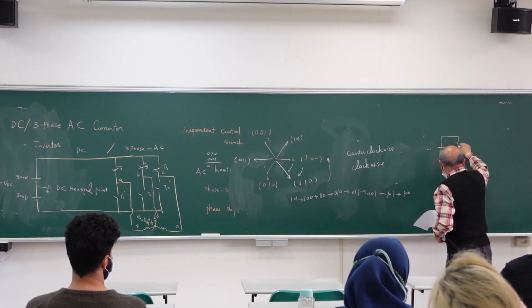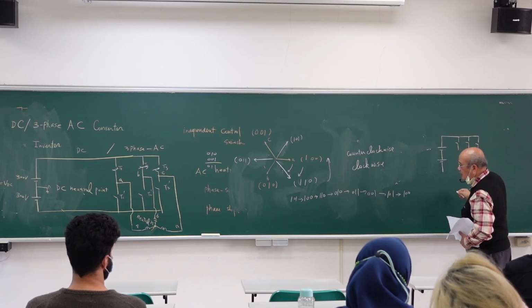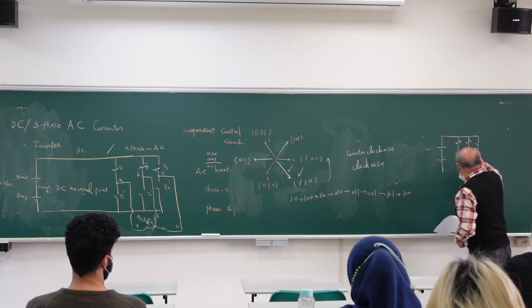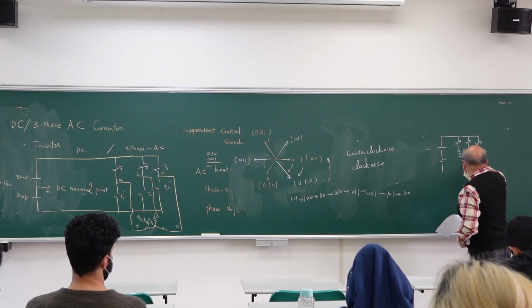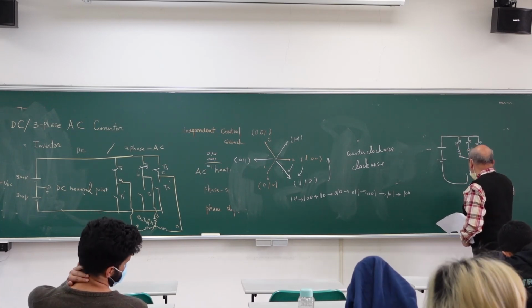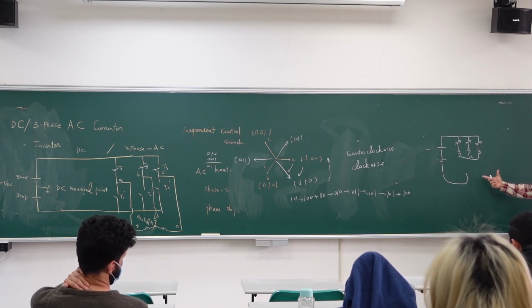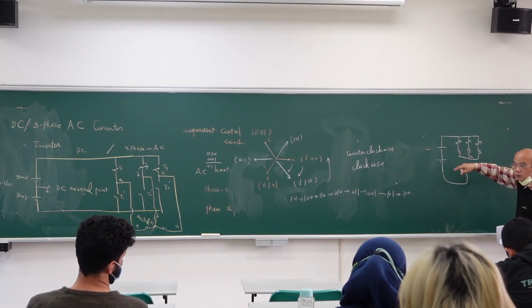we have this one close, this one close, this one close. Then we have motor, close, close. We have motor, and we have neutral, and then we have this circuit. So what is the voltage across the winding? 0. Because you have no loop.